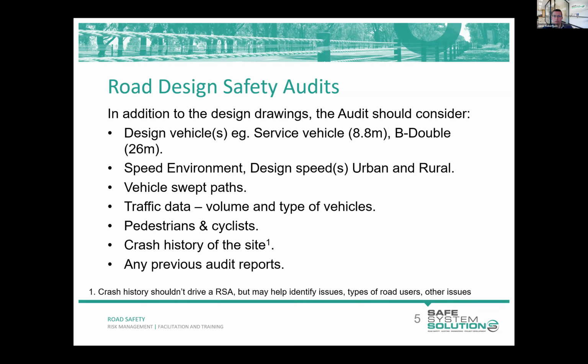Vehicle swept path requirements should be checked as an integral part of the design process. You may have been provided with some swept path diagrams along with the designs. If you have not, and you think it's important to review those, by all means request them from the client or the designer. And if they can't readily be provided, that's a bit of a red flag.